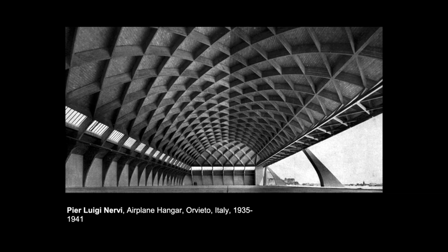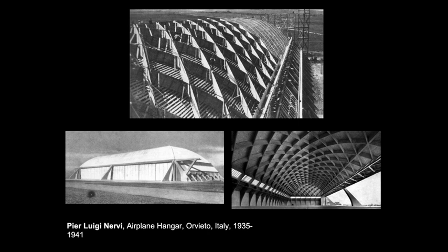And here he goes back to a special wooden construction which was developed by Friedrich Zollinger at the beginning of the 1920s, that depends on the rhomb construction or a diamond lattice construction, like you see it under the roof of this building. And again, he just uses steel concrete to optimize or to extend the wooden construction before.